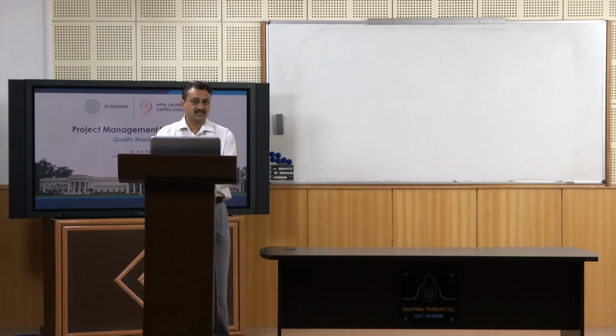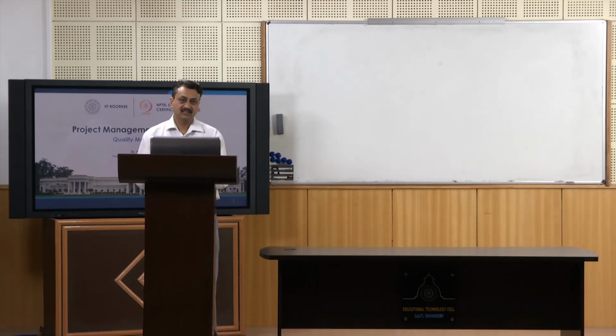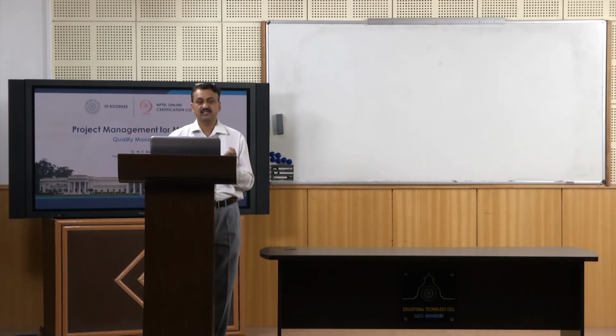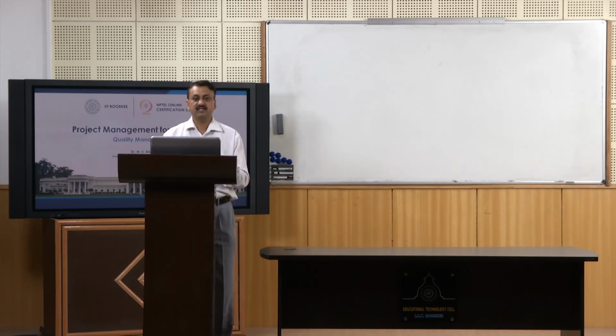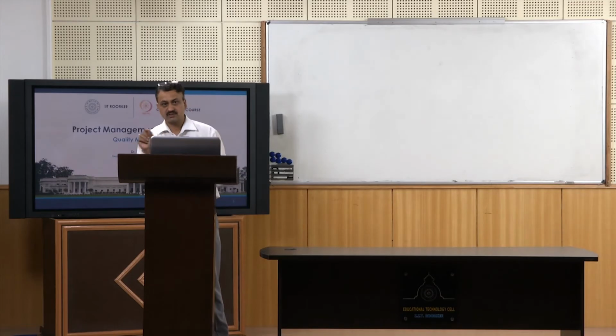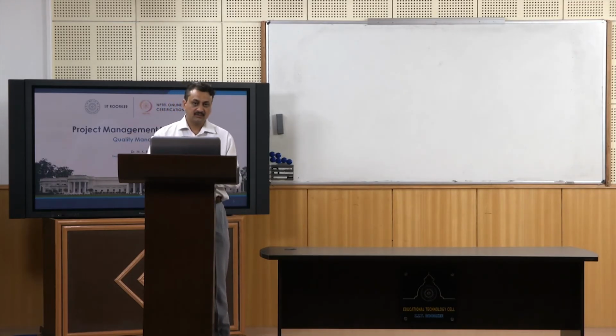So, you should try to make your processes in such a way that you do not produce defective parts, and that can be done through design of experiments. So, before actually producing a product on a machine, you can perform some experiments, that if my input is changed from, let us say, -1 to +1, or let us say if speed of a machine is increased from 200 rpm to 500 rpm, what will happen to surface quality, isn't it? So, you can have different input variables, those input variables will have different settings, right. So, you can have 2 levels setting or 3 levels or 4 levels, right.